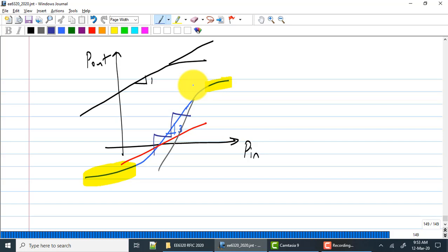That's what I want. How many of you are using Cadence? A good number. About 1/3 of the students. In Cadence you can directly plot IIP3. You do the sweep and plot IIP3 directly. In ELDO, I assume there is also a direct way to plot IIP3.